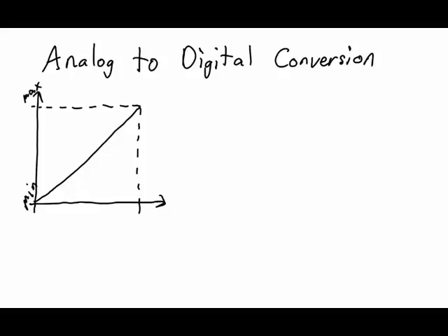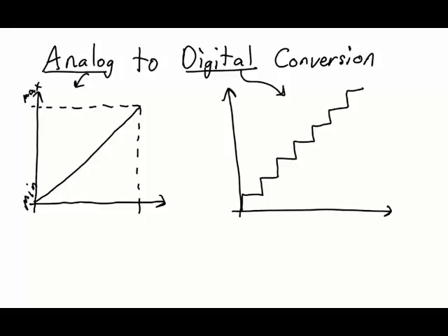We see that the value is analog by noticing that the curve of this sensor response curve is nice and smooth. That's as opposed to the digital value, which looks like a stair-step function. The digital value looks like a stair-step because the y-axis is counts.